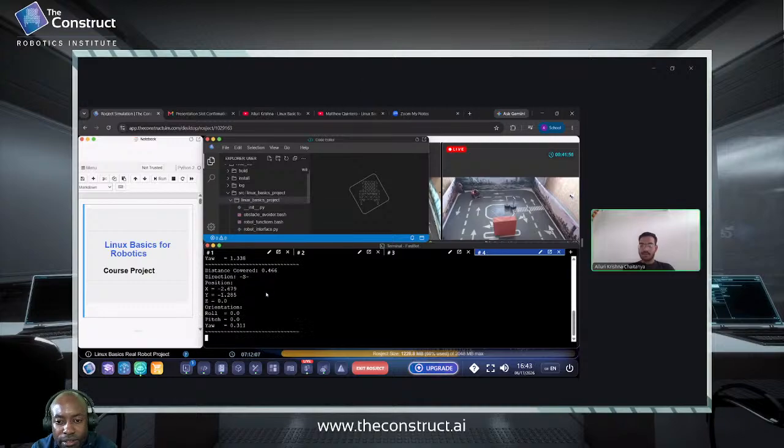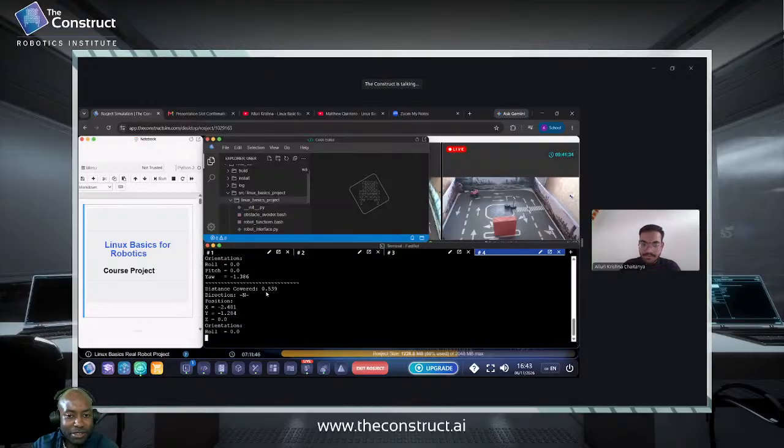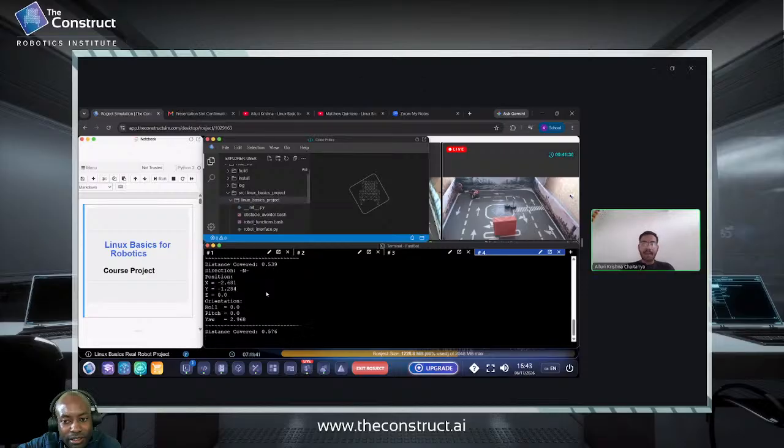Yeah. No, it will move. The thing is, in my program that I'm currently using, it's gonna scan the four directions: your left, front, right, and front, and calculate the best path to travel. So I have set the threshold as 0.7 meters, and if anything is lesser than that, Why is there that? Sorry. Why 0.7? It's more apt and suitable for any rover applications in this case.